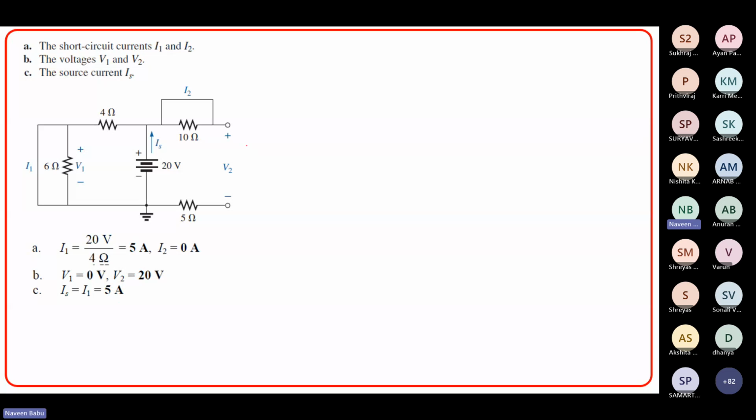It is about voltage. Even if you put a battery, it is an unknown battery, right? It is only our assumption that it can be viewed like this. In the actual circuit, they are open circuited terminals, right? It is our understanding to explain what V2 will look like. So it is a virtual assumption only that we are putting a battery and imagining to apply KVL, like in the previous cases.